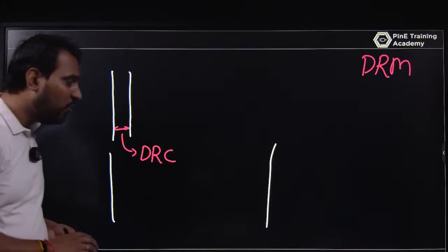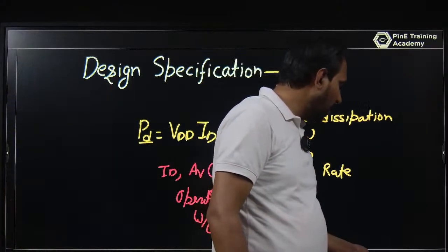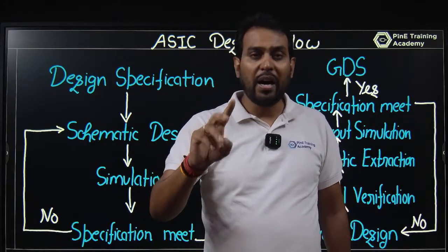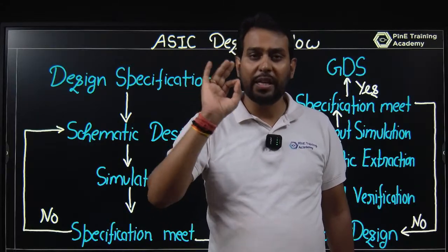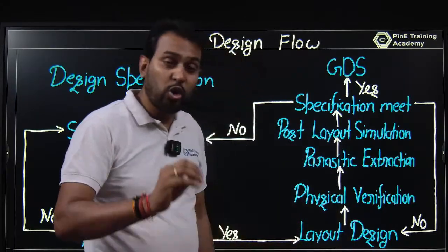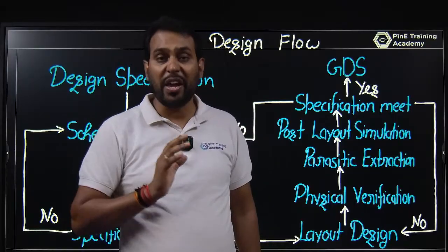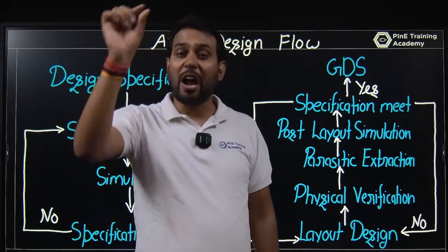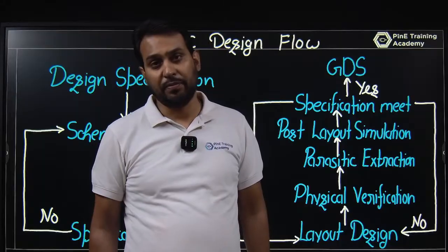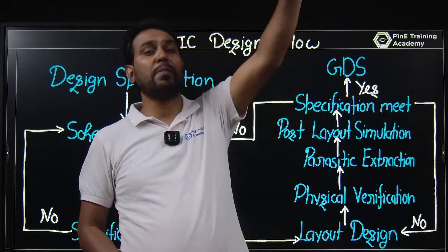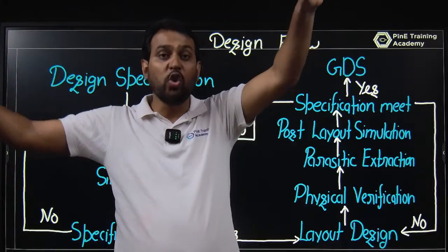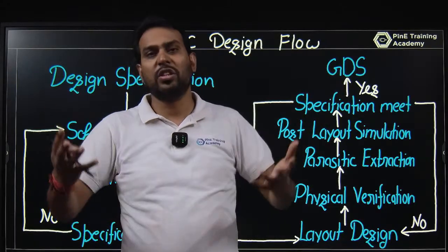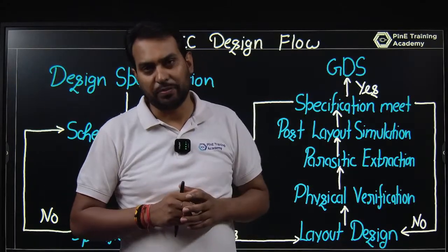Whenever you are designing the layout, you will work on three parts, that is power, performance and area. These three parts are very important. When designing the layout, you arrange the transistors in such a way that your transistors and routing take minimum space. It doesn't make sense to use one PMOS here and one NMOS there; you are wasting your area. And if you waste silicon area, of course, you will have a lot of cost.